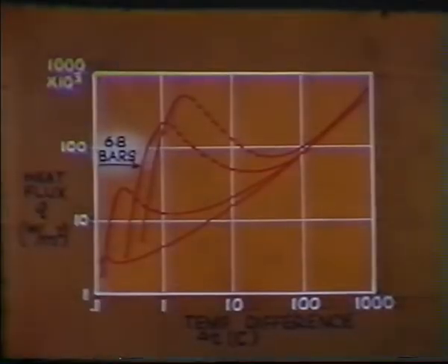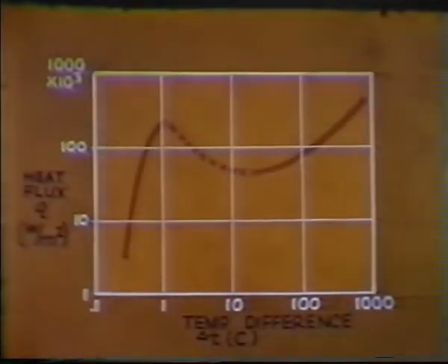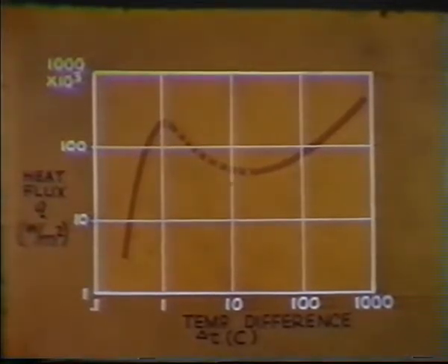The wire is enveloped in a vapor film from which the boiling takes place. The pressure is now increased to 68 bars, and the carbon dioxide is at the corresponding saturation temperature of 27.5 degrees C. The initial heat flux of 200,000 watts per meter square is near the burnout point. During the run, the heat flux will be steadily increased through the burnout point to a value of 300,000 watts per meter square.